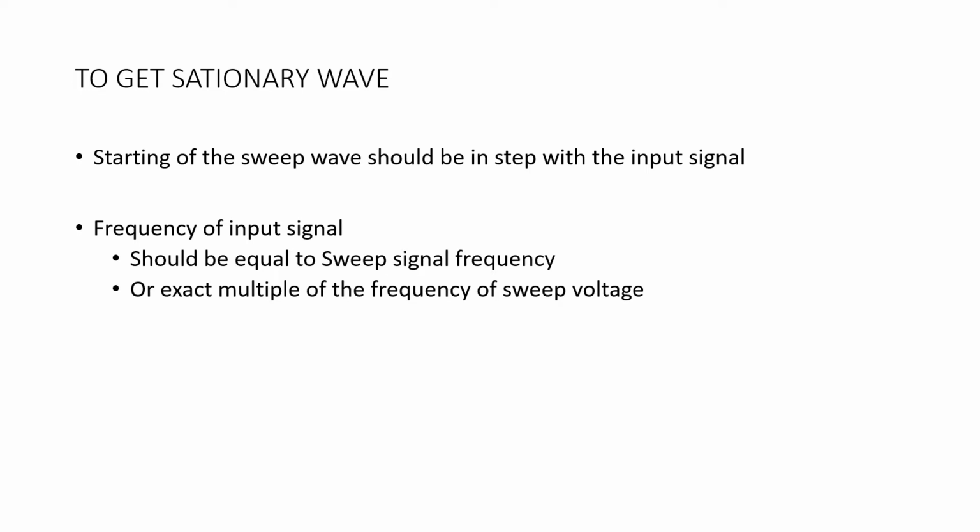That is, the display is not stable, it is not stationary, the waveform moves. So the waveforms on the CRO screen move left to right or right to left. They are not stationary. The frequency of sweep is not an integral multiple of the vertical signal frequency. So, when the wave moves left to right, the internal sweep frequency is less than the vertical signal frequency. When the waveform moves from right to left, the internal sweep frequency is greater than the vertical signal frequency.